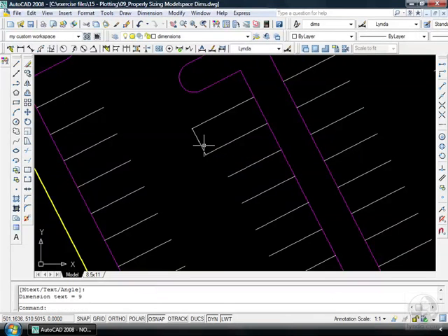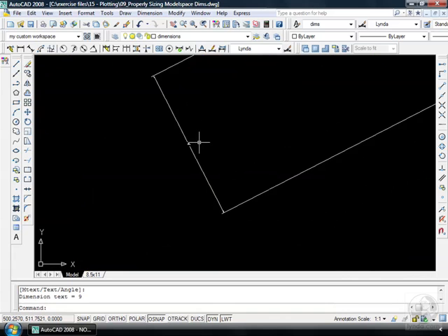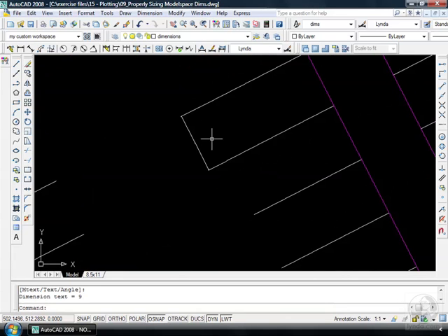At least one time in your AutoCAD career, you're going to create a dimension and wonder, what the devil's going on there? Why is that so small? Remember that your dimensions are conforming to a dimension style, and the size settings that we set in our dimension style represent the size we want our dimensions to appear on paper. So the problem is my dimension is coming in at paper size within the realm of a humongous parking lot. That's why it's so small. That's all right. We can leave the dimension the way it is. Let's just adjust our dimension style.